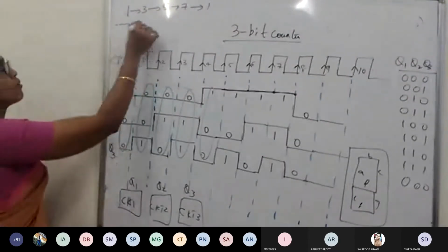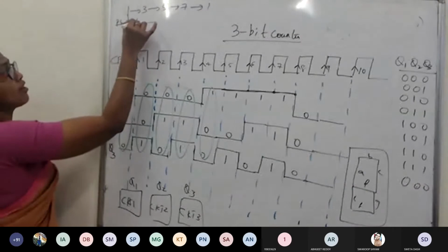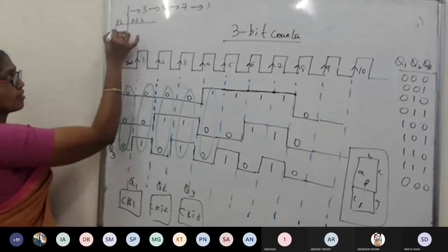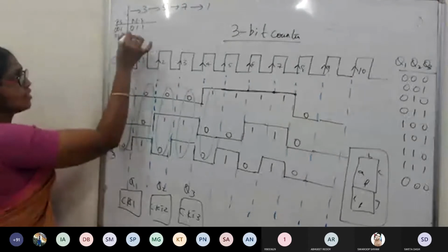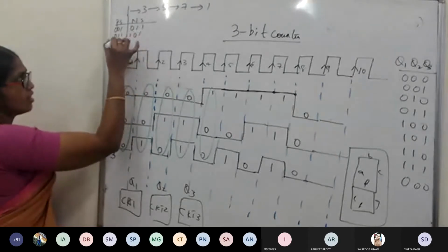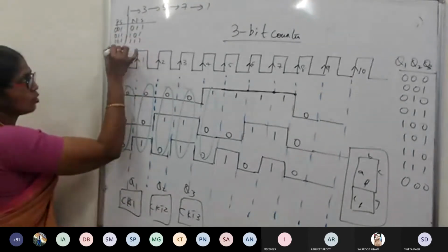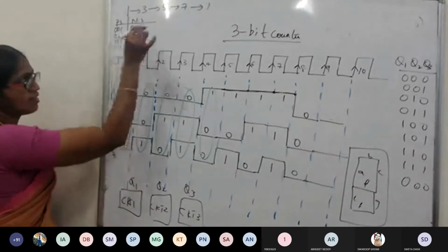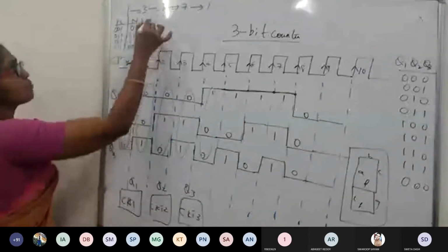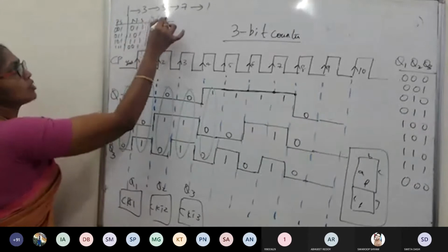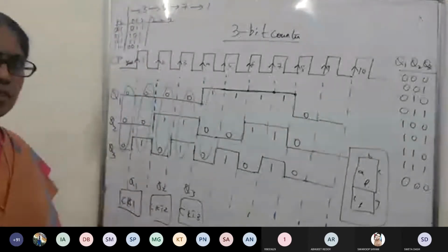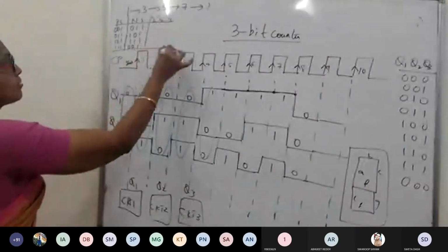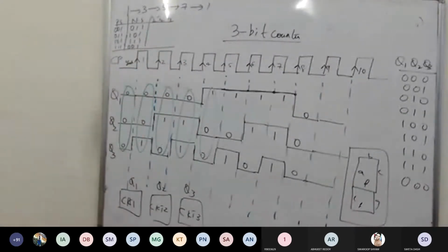Okay. So now, how will my state table be? Present state and next state, I will keep very crystal clear. 0, 0, 1 should be first. Then this is the next: 0, 1, 1. Then this is the next: 1, 0, 1. Then this is the next: 1, 1, 1. If I use a simple T flip-flop, T1, T2, T3, and then make a synchronous circuit, I will get this T1, T2, T3 filling. Can I get the filling?